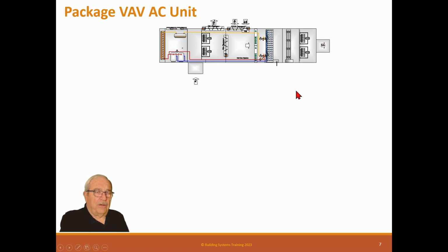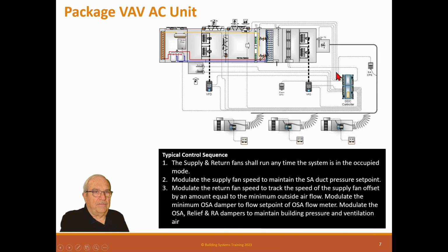Now these are variable speed, so we have a supply duct out here that has VAV boxes in every space. So as these start to close, we have a pressure sensor on the supply duct, and it starts to slow down these supply fans because they don't need as much air, and thus they economize. That's why these are more efficient.